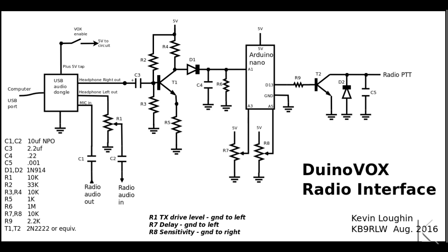I chose that one because there's an LED on top of the Arduino, and it was nice to have a visual aid while debugging the software. You could use any of the other digital pins if you wanted to. That's fine. I chose to leave it that way, so I had that nice little LED on top of the Arduino that's lighting up when the push-to-talk keys. If you had a clear plastic case you put it in, that might make a nice little visual addition.